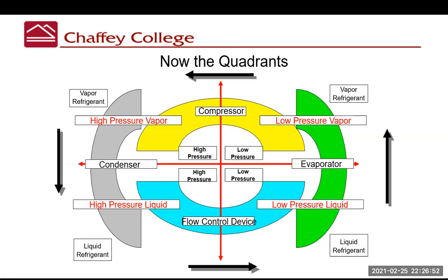Refrigerant compressors are not like compressors that you have at home where it compresses and builds up pressure in it, and it holds that pressure. The compressor is simply pushing the refrigerant around the system. The compressor itself does not build up pressure inside a cylinder like an engine does. It simply takes the refrigerant in one side and pushes it out the other. The only reason the pressure increases is because there's this restriction device halfway around the system.